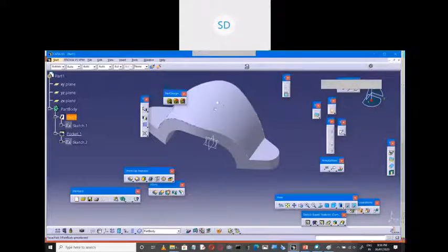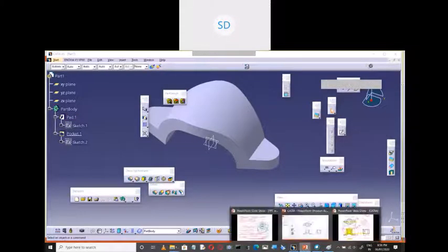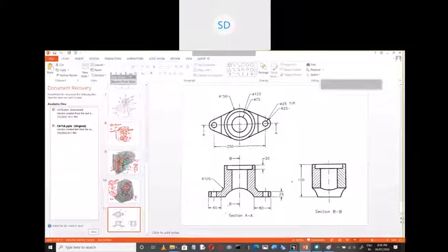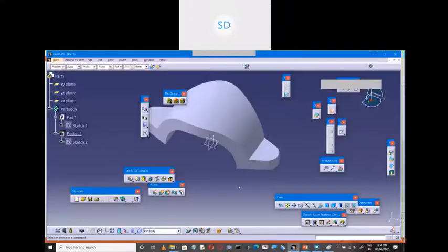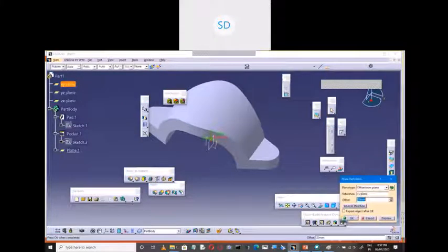Next, over this one, you need to produce a cylindrical object, a circular object, and along with that, you need a hole of counter bore. Now look out. What I'll do, I'll go for reference plane, reference elements here. Now I'll click on XY plane. With respect to XY plane, I want to create one more plane here. So distance is 150 mm.